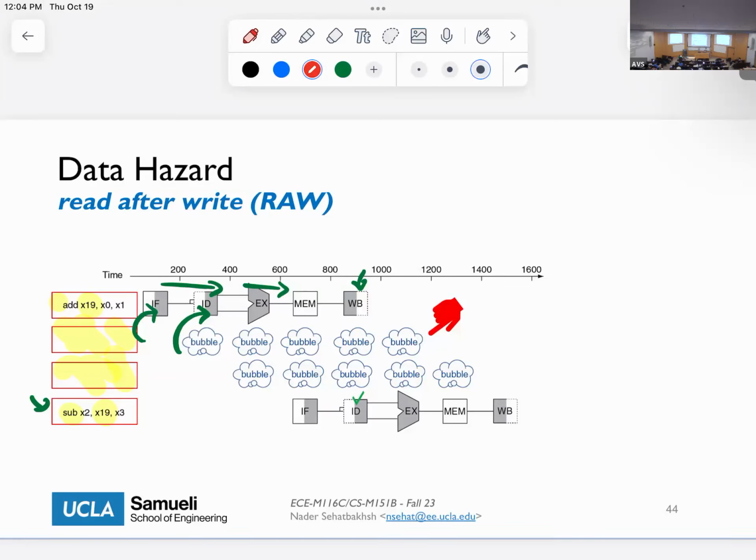The reason that we had this problem was that in a pipeline processor, we start overlapping things. So there will be two cycles where the previous instruction hasn't been finished and the write to the register file hasn't been updated. And if you try to read the destination register during that 2-cycle window, you're going to get into the problem of RAW data hazards, right?